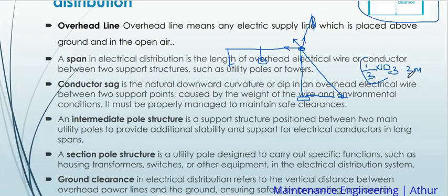This is the same formula that works for HV. That is the primary. And for HV, they are always somehow high because they use poles of 14 meters. And sometimes when the topography is okay, they use poles of 12 meters. Still the same formula applies. I'm now calculating the distance here, which I may call x, from the pole up to here. That is the standard of a stay. A stay is that support that is trying to support the pole not to fall down because of the tension on it.